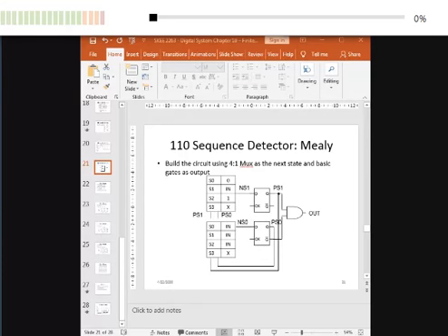Okay, some people combine these two in one finite state machine. But what happens if you want to expand into 8 times 8 multiplier? That's crazy. You have to redo the finite state machine. If you split them, the counter is the only thing that you adjust. That's why it's always good to split control unit into several components.